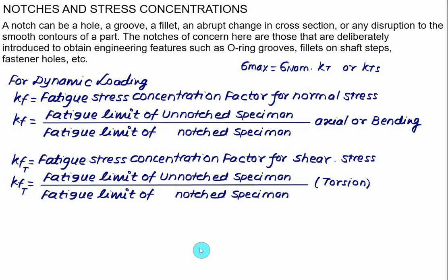And that difference from the static to the fatigue analysis comes mainly from the fact that the notch stress affecting the fatigue life is not the maximum stress at the notch, but instead it is the average stress acting over a volume of material close to the notch. Adding to this, any crack that is initiated at the notch will be growing into the region with stresses that are much lower than the stress concentration.